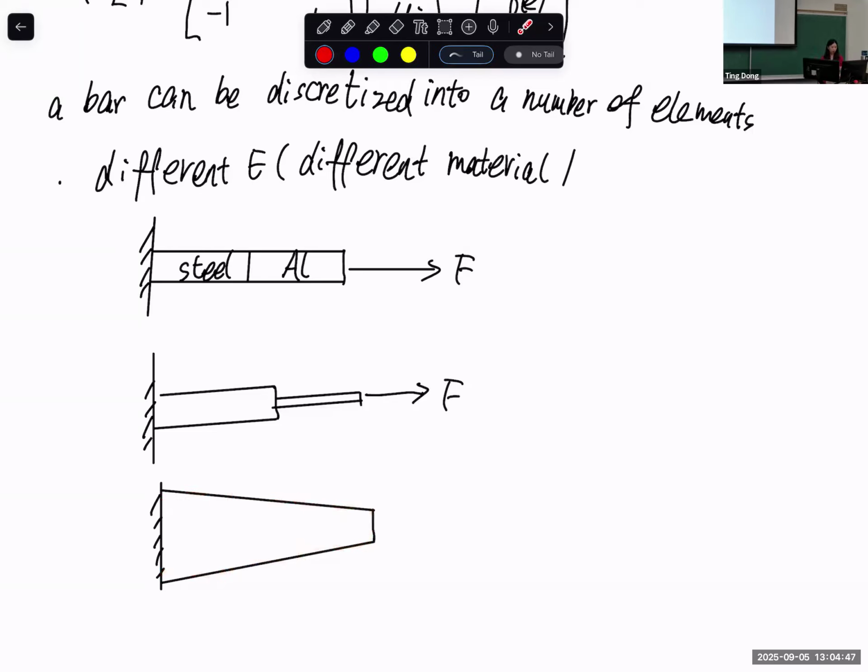And of course, the more elements you use, the more you converge to the accurate result. So with FEA software, you can do a convergence study to see how it changes, let's say from 3, which I just showed as an example, to 10, to 100, to 1000. It's hard to build a matrix and solve by hand or use MATLAB, but it's very easy using FEA software like Abaqus or ANSYS. So this can be done using FEA, and we need to discretize into different numbers of elements.